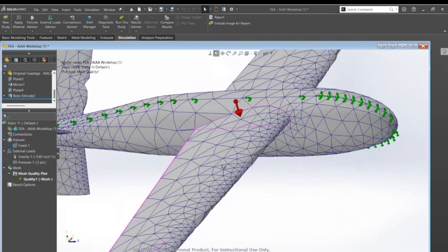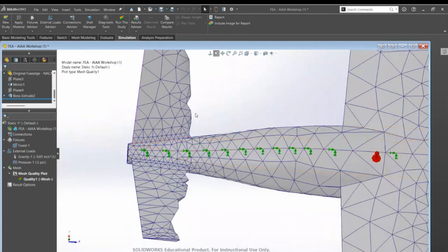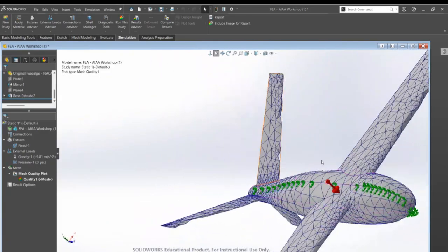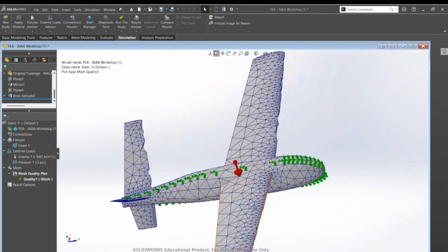And you can always up the values, and now it's all like a shark bite or something, because that's how it models it now, and that's what it is in the mesh. So you can do whatever mesh you want. It does affect the accuracy though. Then we'll go ahead and apply.